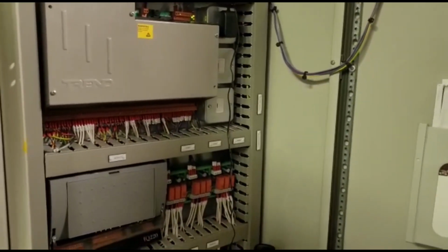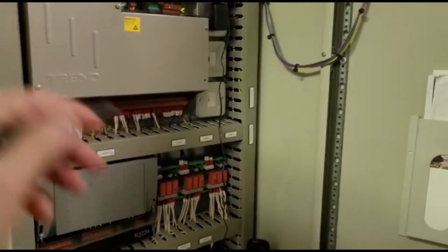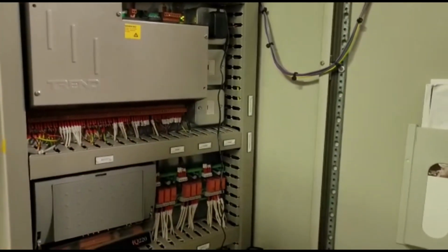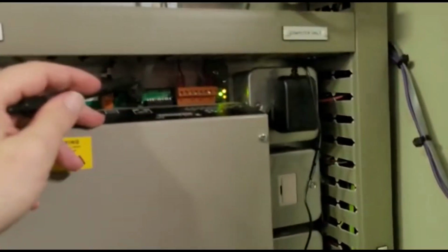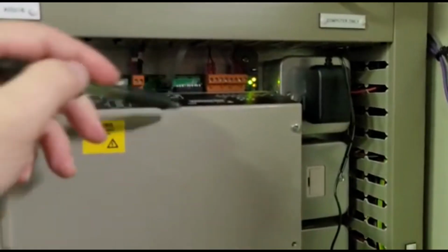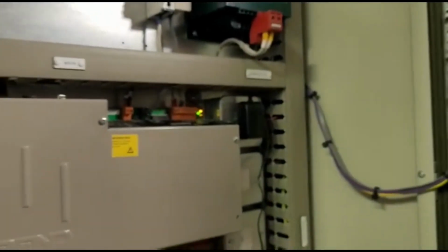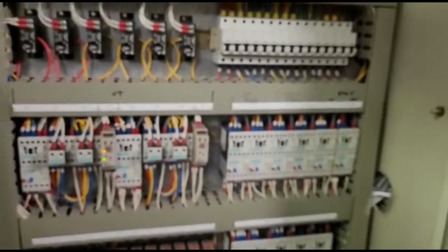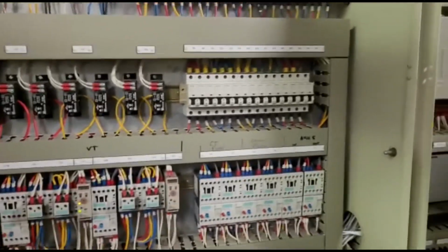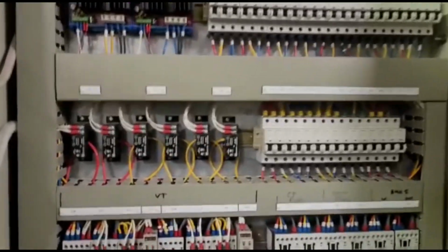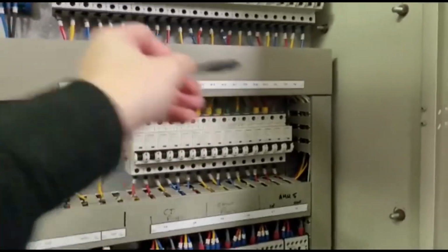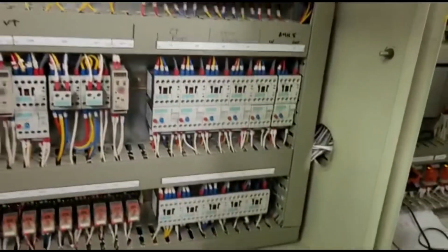We don't use ladder programming here on Trend. It's like a wiring diagram that we work to when we plug in with our laptops. We just plug into the port here, take that out, plug into the port, and we get in with our laptops. So you can usually diagnose any problems straight away. This lot, this is all your switch gear for your plant room. Yeah, a lot of it works on 24 volt, but obviously all this lot is either 415 or 240.